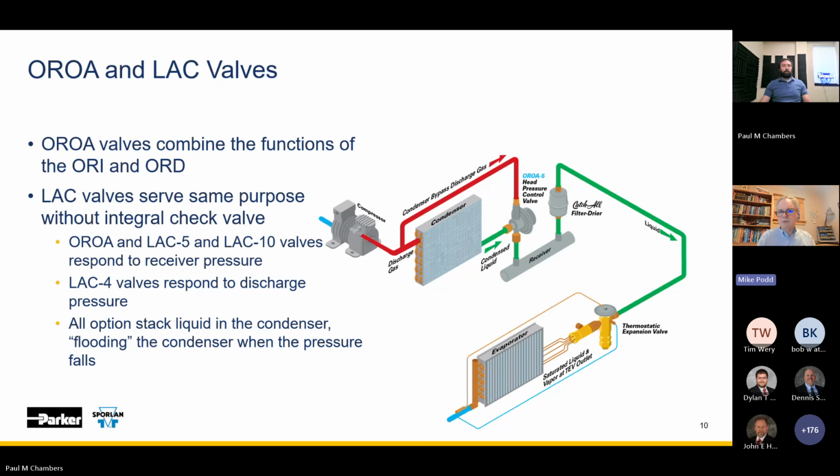So when we say the TX valve will act undersized in the wintertime without adequate head pressure control, the valve sizing is the same. The refrigerant has the same net refrigerating effect, same BTUs per pound.